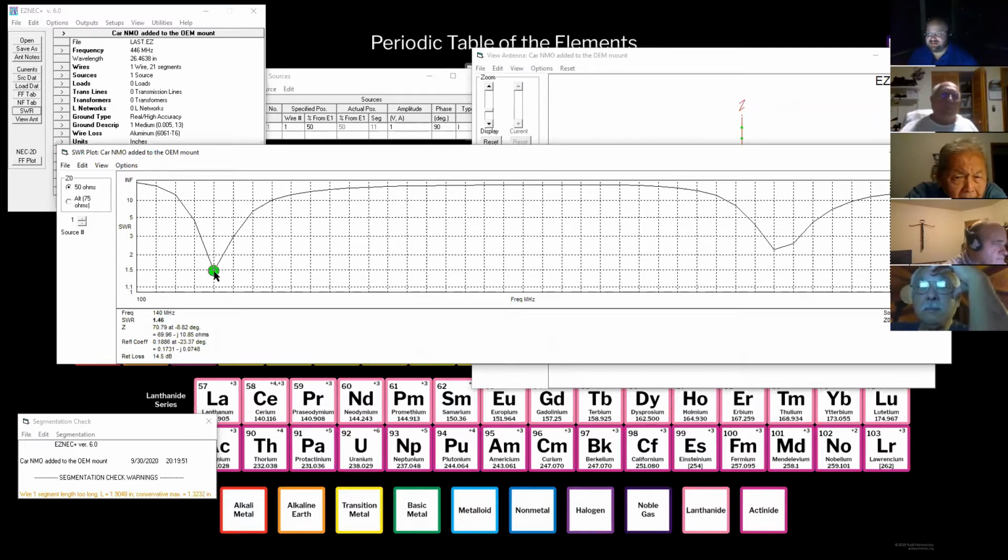So it says that I'm resonating at 140 megahertz and I'm resonating at 430, 440 megahertz, roughly, because I've got relatively low resolution here. So this would be the quarter wavelength of this wire, and then this is a 3/4 wavelength, because at every odd integer multiple, your wavelength's going to be resonant. The pattern may not be what you want, but it's going to be resonant.